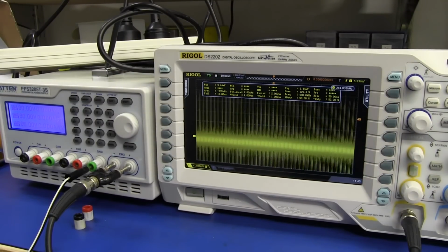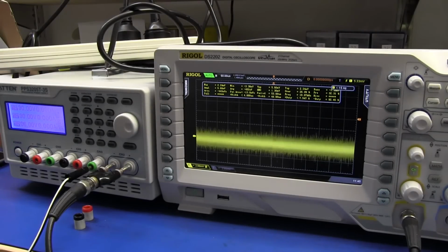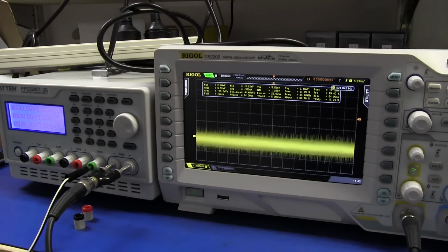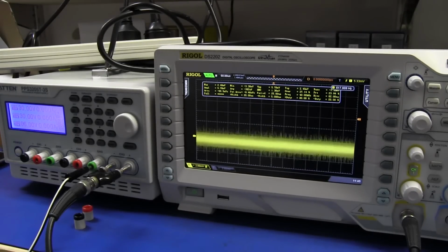They're the LED lights I've got up the top, and they're not even supposed to be PWM, and they're supposed to be constantly on at maximum brightness there. I can turn my other set of LED lights above, does absolutely nothing, but those lights I've got up there, big switching noise. So we came full circle there, and we're getting closer to eliminating everything.